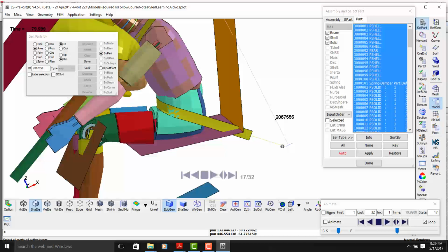But it does not matter. In DYNA, we always model a pretensioner using a retractor. Now what do we do here? If it is here, the real retractor, we can have a pretensioner like we have in this model. But on the anchor side, what we do is we put in a fake retractor. That means we model another retractor just to model the pretensioner for this part.